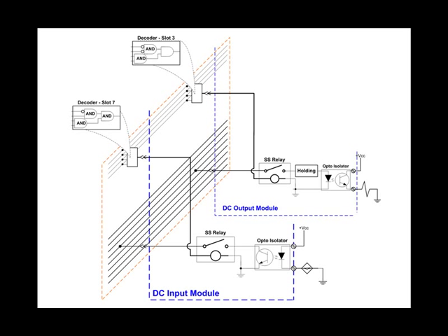And when it comes time to send out the output states, which are stored in memory as a result of the logic, to that slot, it will be one word at a time until all 32 words are transferred from the processor's memory into the DeviceNet scanner card's memory. This sequence is repeated to transfer the 32 words from the controller's memory to the 32 words in the DeviceNet scanner card for the outputs.